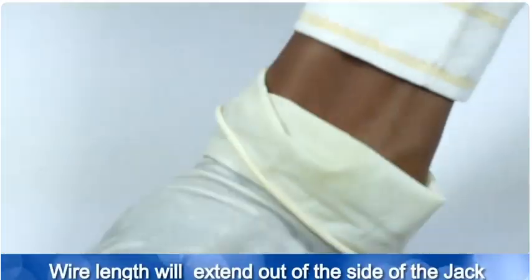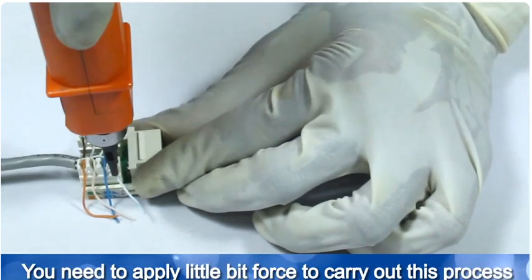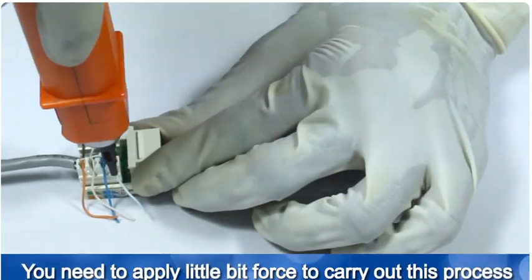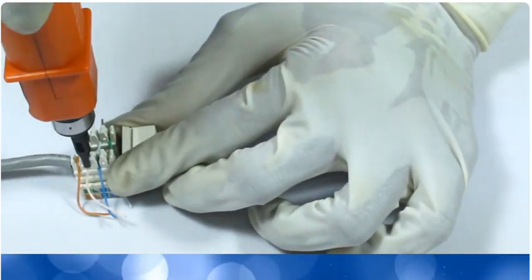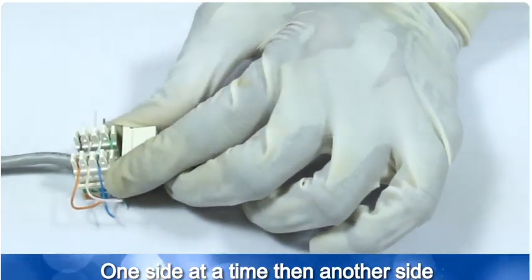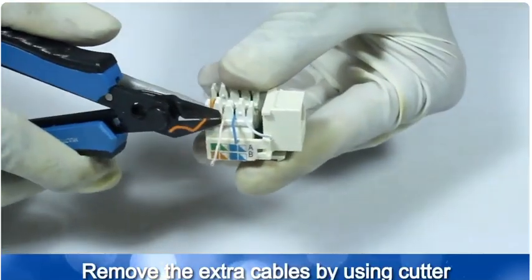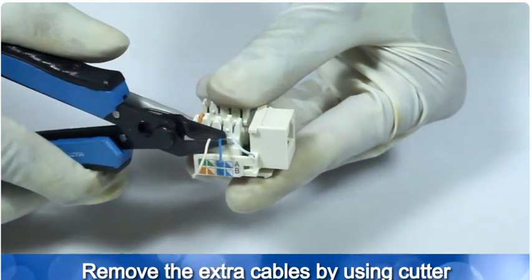In this process, excess wire length will extend out of the side of the jack. You need to apply a little bit of force to carry out this process. It is also recommended to punch down one side at a time, then another side. Remove the extra cables by using cutter.